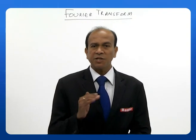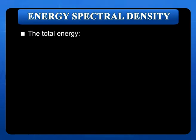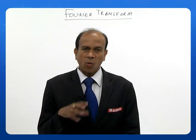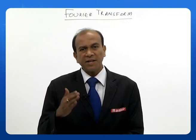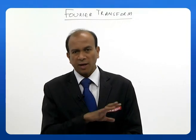Now let us look at energy spectral density. So what does energy spectral density say? The total energy E is given by, as you see here, the integral from minus infinity to plus infinity of mod g of t whole square dt. That will again be equal to the integral from minus infinity to plus infinity of mod g of f whole square df. So this is the energy under the curve. If I calculate the area under the curve, that area will give me the total energy of the signal, whether it is in the time domain or the frequency domain. So these two will give us the total energy.